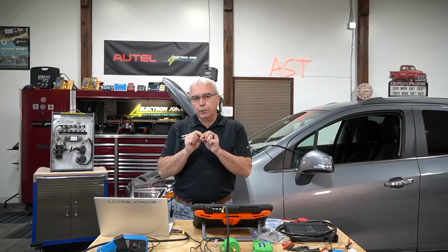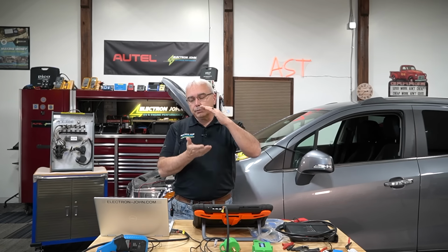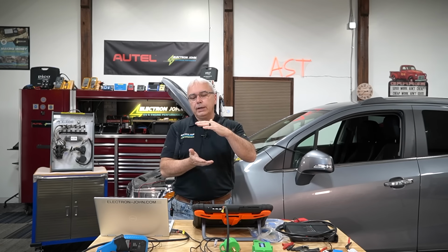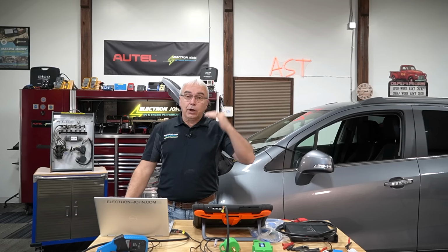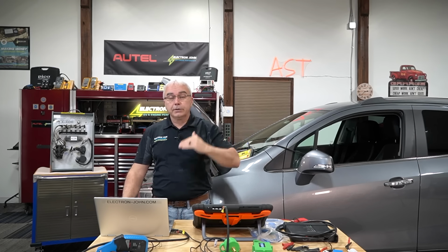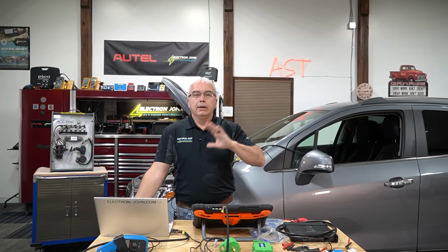And what I did is, when I removed that shorting bar, it took all of those modules off the network. I still had my lab scope and everything hooked up, and I used a set of jumper wires, and I put one module back on the network at a time, and I was monitoring for a good communication signal. Now, if I saw it going from the 7 volts down to 0 volts, I knew that that module, that circuit, I should say, was not the problem.